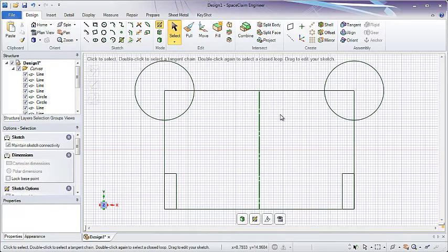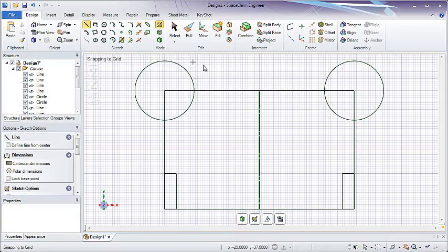What this means now is that anything I create on one side of the model will be created on the other side. Notice 2 quick sketches makes this on one side and makes this on the other side. To remove these, I'm simply going to undo by going to the Quick Access toolbar and pressing undo.